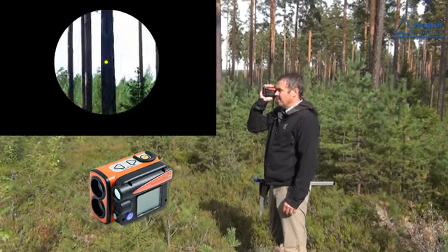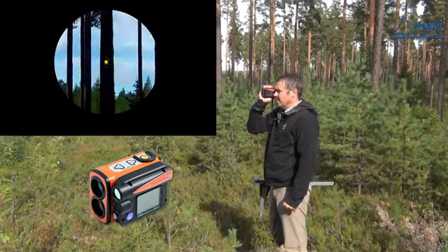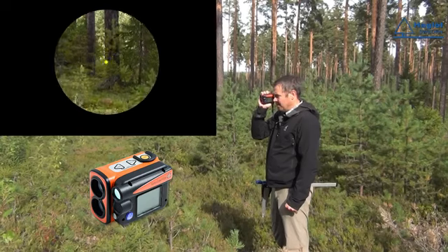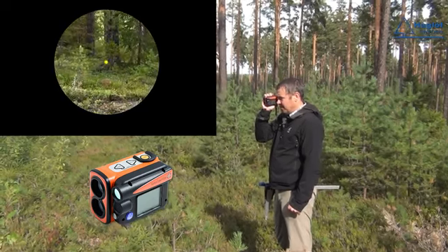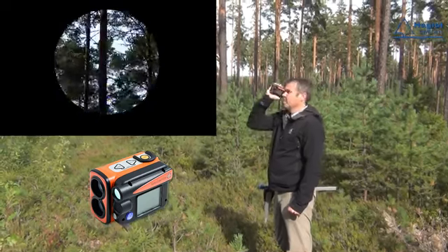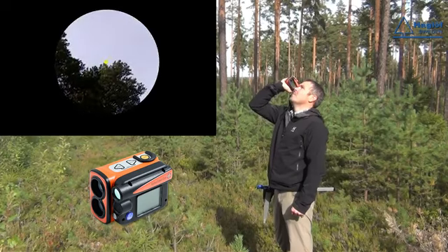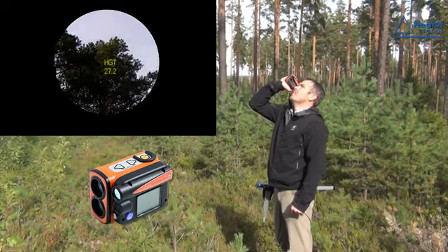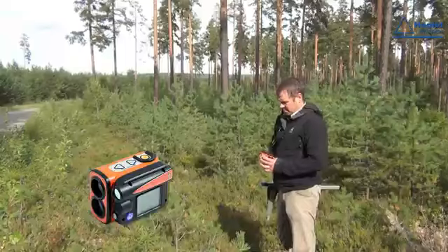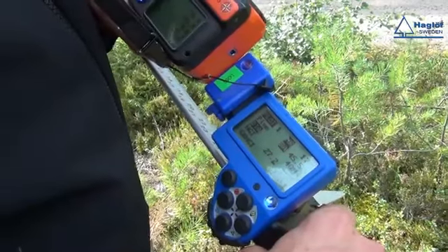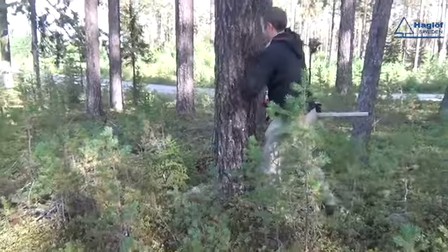He first fires a laser to measure the distance to the tree. Then he measures the angle to the bottom of the tree, and finishes the measurement by measuring the angle to the top of the tree. Then the height of the tree is presented in the instrument. The height is then recorded in DP2, but it can also be transmitted with infrared.